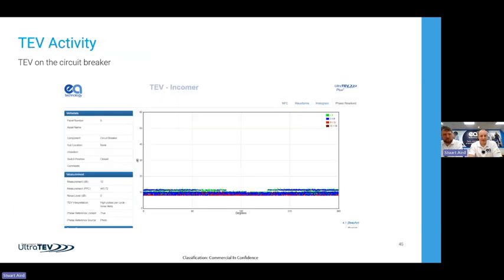But just to reference back to transient earth voltages, they were across the board pretty level, around 10 dB. As we've seen a lot of phase plots that are quite classic partial discharge, they've got the two groups, 180 degrees apart, things like that. In this case, we've got a plot that's completely flat right across the sine wave. So it's unlikely to be partial discharge related, as some areas of this would have 0 volts. But obviously we have got a pretty strong partial discharge source within that board still.